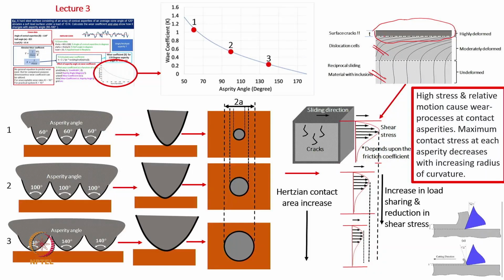So this is the important aspect. Now we see surface roughness plays an important role. Reason being, we have already analyzed, or covered in lecture 3, the wear coefficient, and we say that above 60 degree only that is lesser than 1, and then we can see how the wear coefficient is decreasing with increase in contact angle, or maybe say the cone angle.